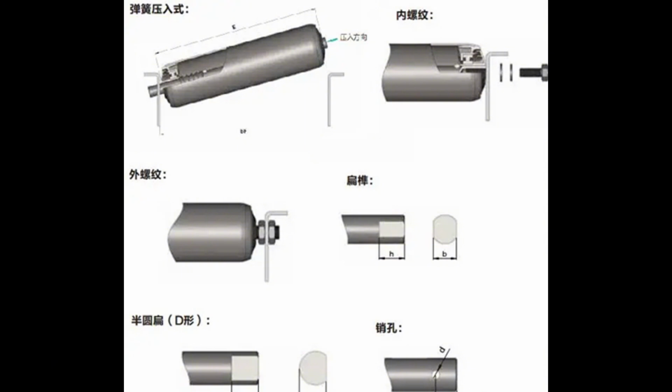About load and load capacity. Load refers to the maximum load that can be carried on the drum that can be driven. The load is not only affected by the load of a single drum, but also by the installation form of the drum, the transmission arrangement and the driving capacity of the transmission parts. In power transmission, the load is decided by the drive. Load capacity refers to the maximum load that the drum can bear. The main factors that affect the load capacity are the cylinder, shaft, and bearing, and it is determined by the weakest of them. In general, increasing the wall thickness can only enhance the impact resistance of the cylinder, and has little impact on the load.